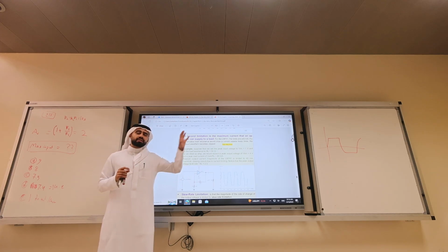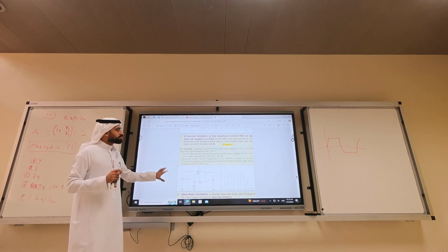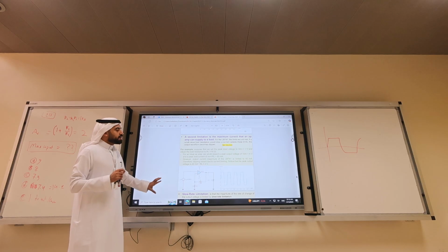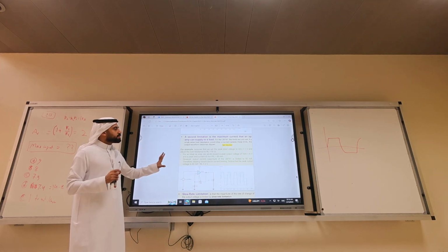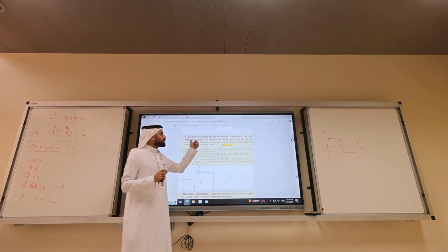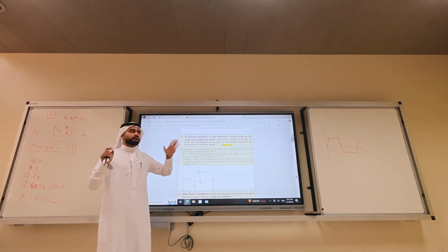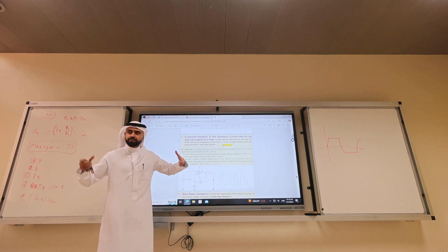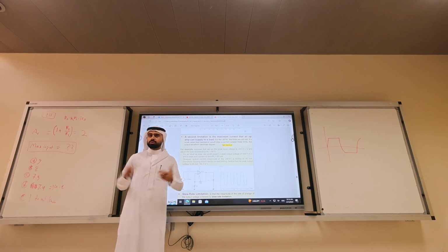If you cannot drive the load, if you cannot drive the speakers, for example, if you cannot provide enough current, then we will have a problem: the maximum current the op amp can deliver. No matter what you do, you cannot deliver more. The op amp has to be a more expensive one. Now, how do you know the maximum current? You have to go to the data sheet.